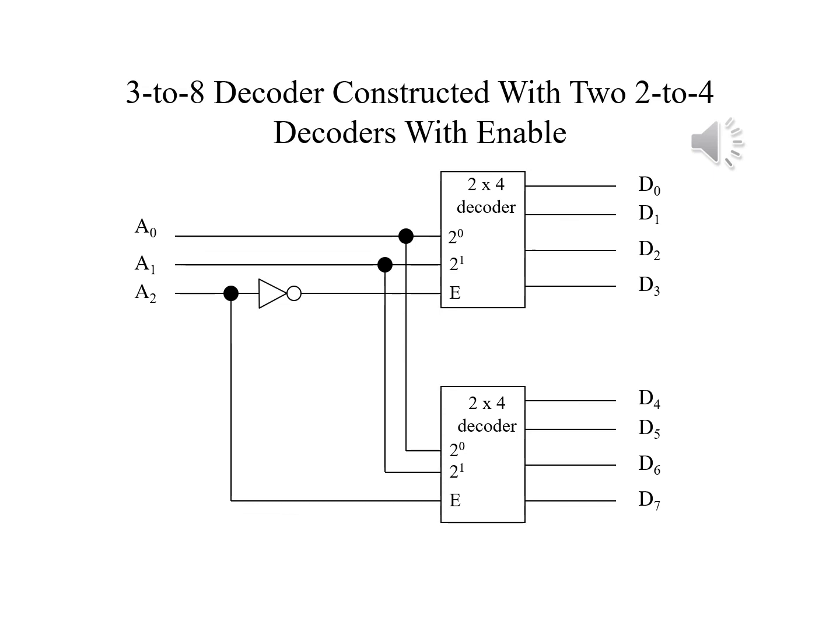Now, in the case of the enable, A2 complemented goes into the lower decoder, and A2 goes into the enable for the upper decoder. If what I have, for example, is 0, 1, 0, I'm giving 1, 0 as the inputs, and the opposite of 0, 1, into the enable. That's for the lower decoder. So it will register D2 as the answer.